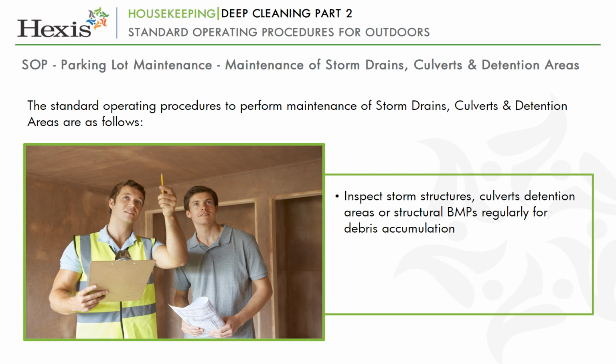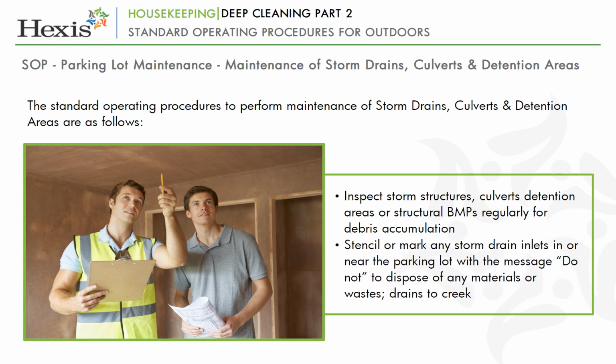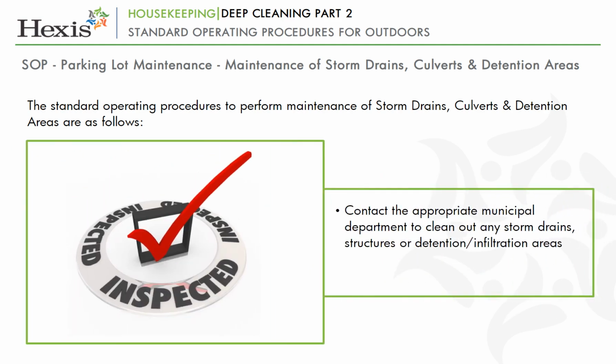Clean out as needed. Stencil or mark any storm drain inlets in or near the parking lot with the message, "Do not dispose of any materials or wastes, drains to creek." Contact the appropriate municipal department to clean out any storm drain structures or detention or infiltration areas. Cleaning frequency should be clearly defined.